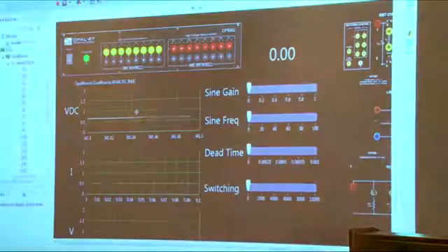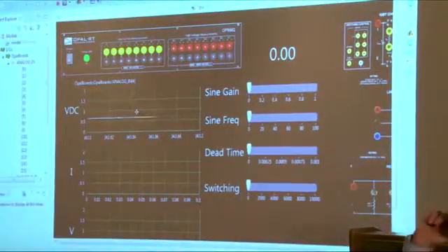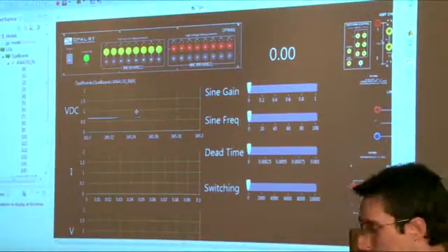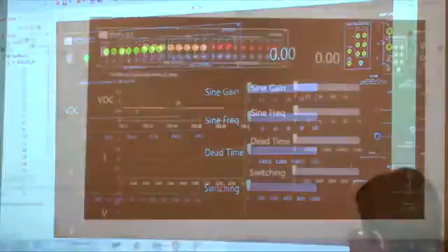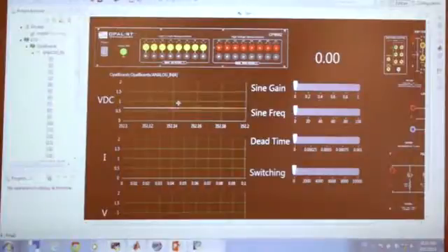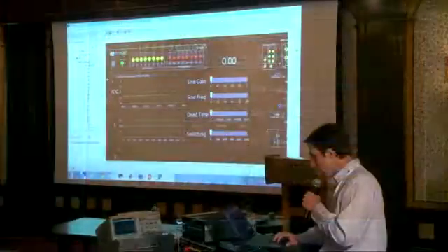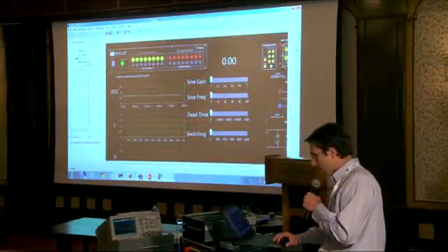So now, without having any models, I just said I want to have the analog input number 4 from the real-time simulator, so the FPGA that is doing some acquisition, and I just routed this to a scope directly. We're currently using a National Instruments LabVIEW panel here, so it's pretty simple. You don't have to do any LabVIEW code. You just open a VI, you drag and drop some components, and then you can assign directly components from the FPGA to some GUI.